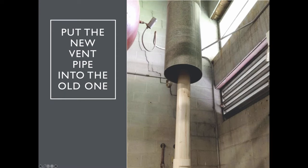This job was a college we went to, and they replaced a water heater with a condensing water heater. And they didn't know what to do with the vent, so they put the PVC vent into the old vent. And when I got here, there were flue gases filling this whole space, and the combustion air was blowing it all over the place. And I shut it down.